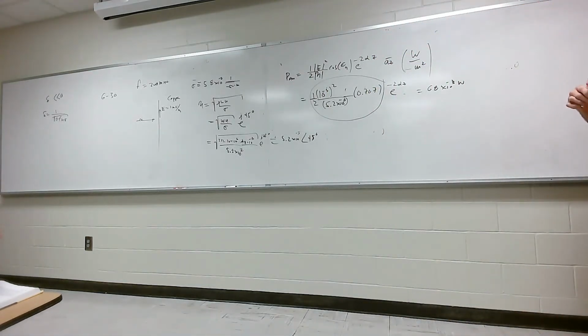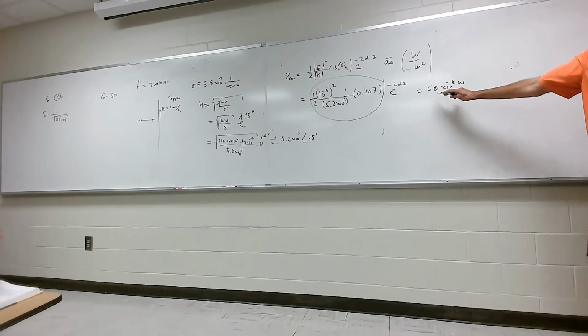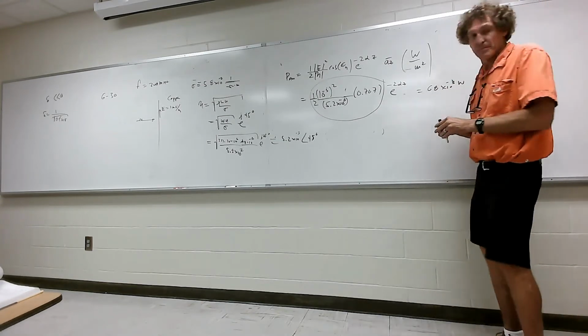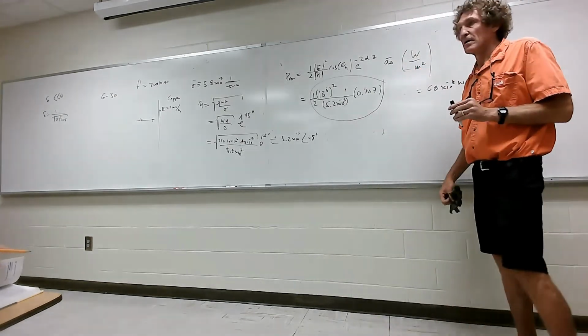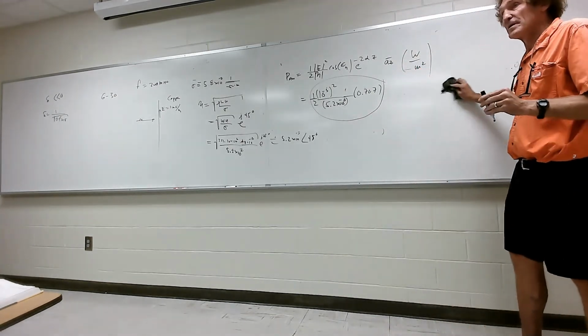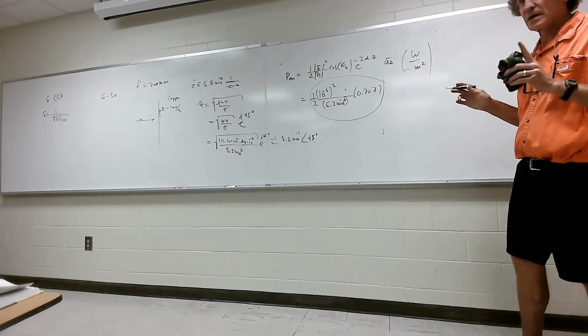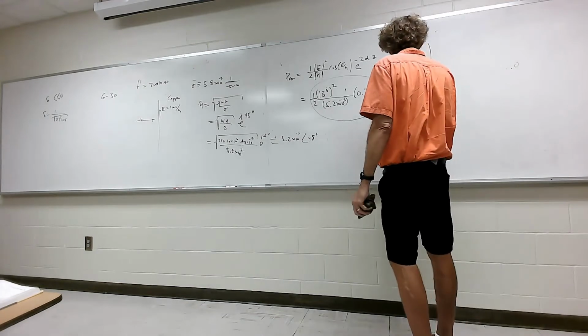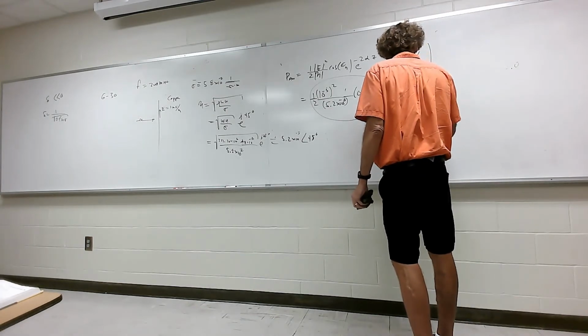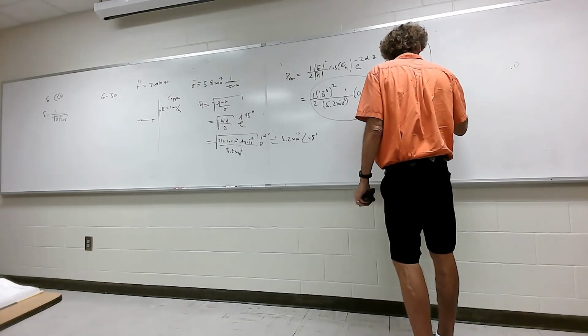Is the answer wrong? Yeah, he did. He's got 96 microwatts. Hold it. Can anybody confirm that this is right? I didn't square on top. Yeah, the units are wrong. What is the answer? 68 microwatts. Is that correct? Yeah. Is that in the book? The book says 96, because it didn't multiply by 0.707. It should be 68 times 10 to the minus 6 watts.